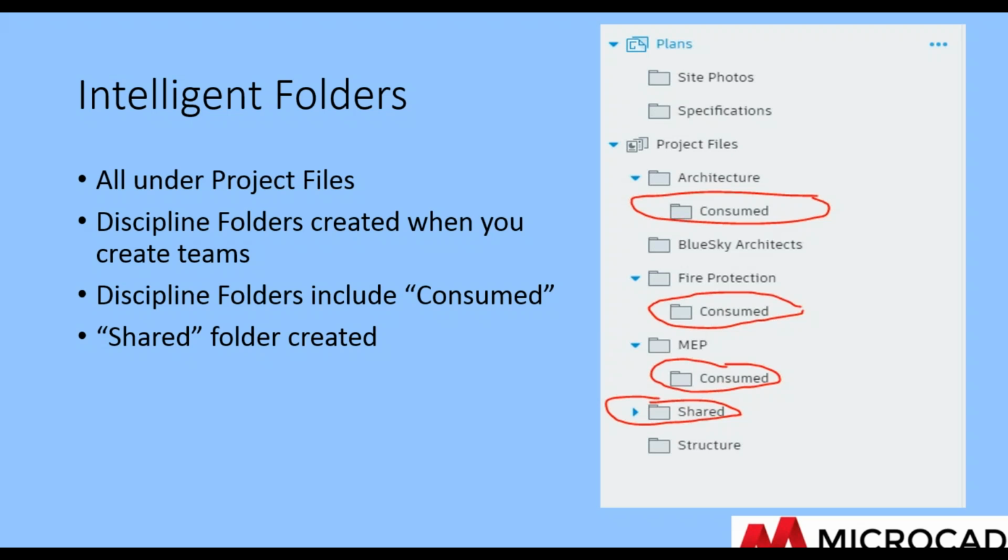Autodesk recognizes that different situations require different approaches, so they create a system that allows you to use BIM 360 with one workflow for a traditional design bid build project and a different workflow for a design build or IPD. Linking Revit models to the different folders will give different workflows, as we will see later.